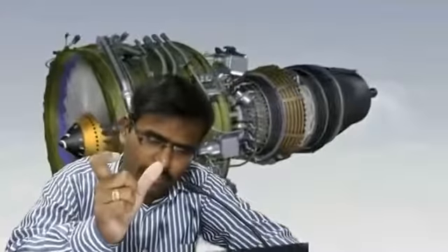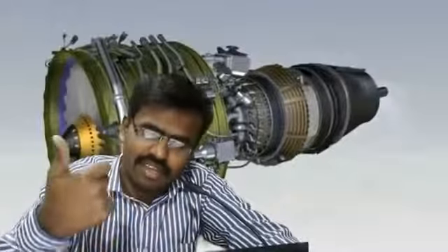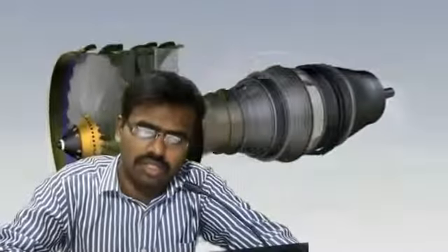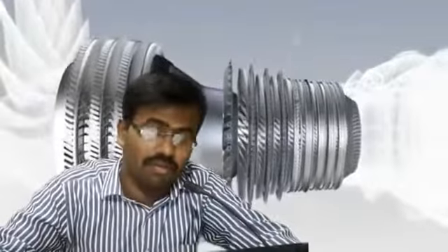The principle of working is, first we have a compressor. Then the air from the surroundings enters the combustion chamber through the compressor. Right, now fuel is given to this combustion chamber. It gives fire. Right. Then the jet of gas is produced. That jet of gas is given to the turbine. Then from the turbine, the flue gas is exhausted out and given to the jet pipe, or it may be a nozzle. Right, this is the principle of working.